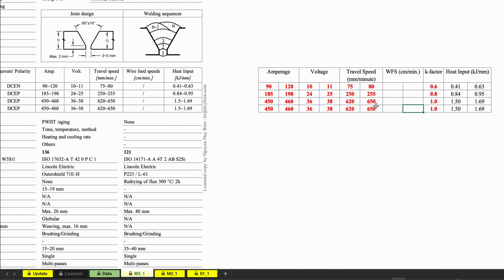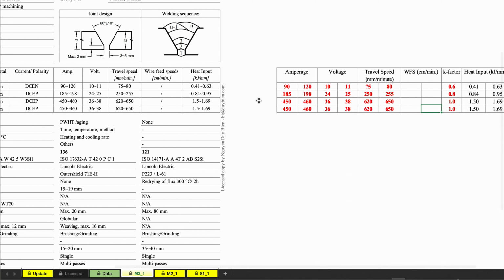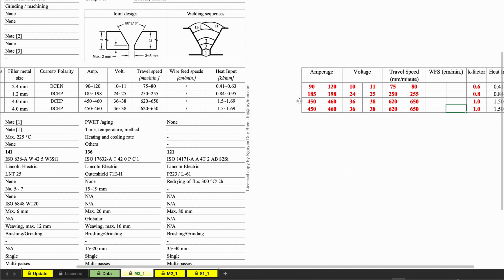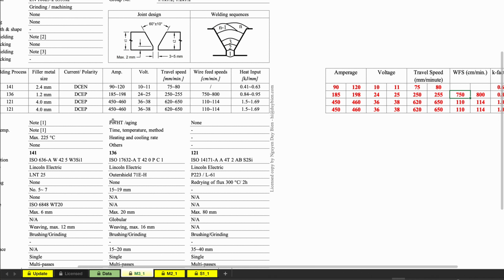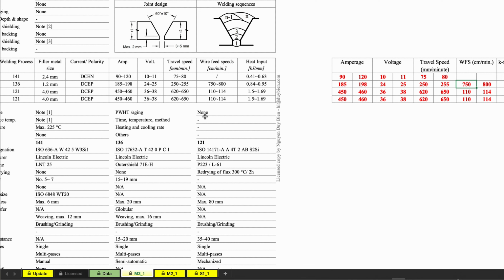Yeah, and maybe control during the adjustment in the welding machine. They can adjust from there. Okay. If not, you should put information just like here exactly. We have the welding machine, very important. The reason is when we are using automatic welding and mechanized welding, it should be recorded with the welding machine.